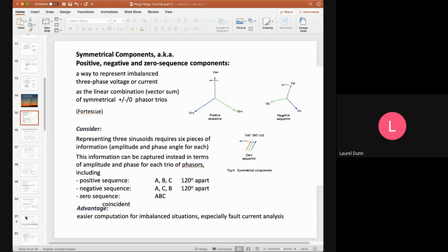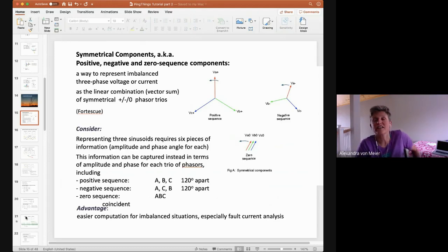Okay. And then for phasors that would just report positive sequence vectors, it seems like there's information loss associated with that. What happens when there is a disturbance? You can't see it. Oh no. So that's our second category of lossy compression, right? So it's information loss from the phase imbalance, and we already lost information when we chose to represent the waveform as a sinusoid, because in reality it's not a sinusoid. So everything that's in there in terms of harmonics and distortion and other imperfections is not going to be captured.